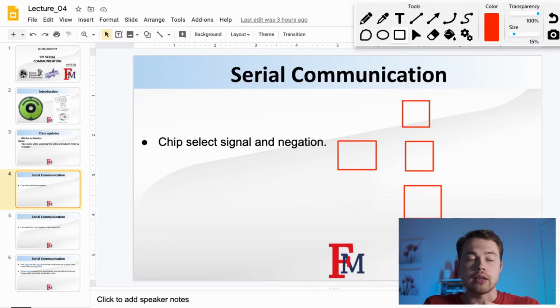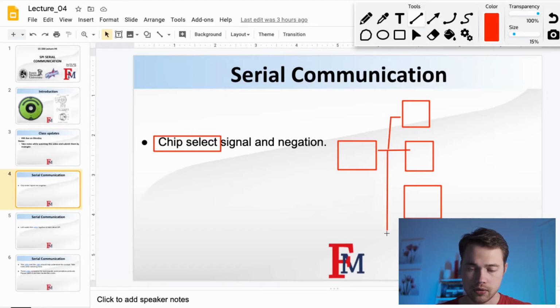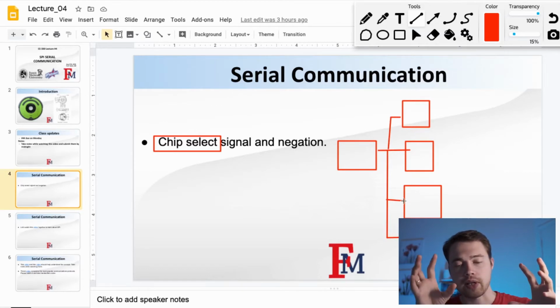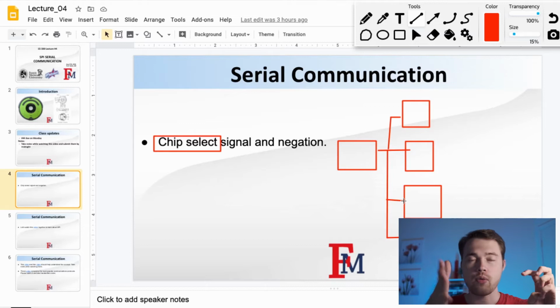That's why the stuff we'll be talking about today, which is SPI, another way of communication between two devices, another protocol, has so-called chip select. So what does it do? It basically allows you to have one device talking to multiple devices. So you have one device, and you're allowing that device to control, let's say 4, 3, 2, 1. In the simplest case it's 1, of course, but I don't know, 5 multiple devices.